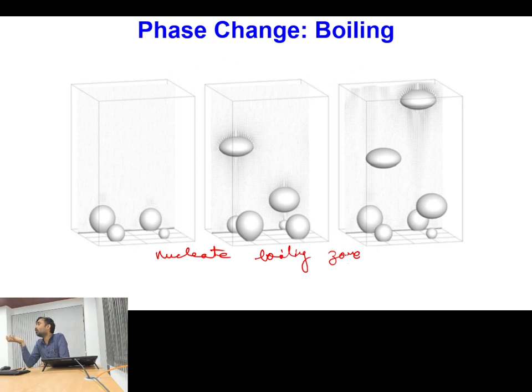So these are nothing but called your nucleation sites. Okay, and from these nucleation sites you can see that your vapor volume is growing. Once its size becomes sufficiently large, it leaves the surface, and again a new vapor volume starts evolving from the residue.